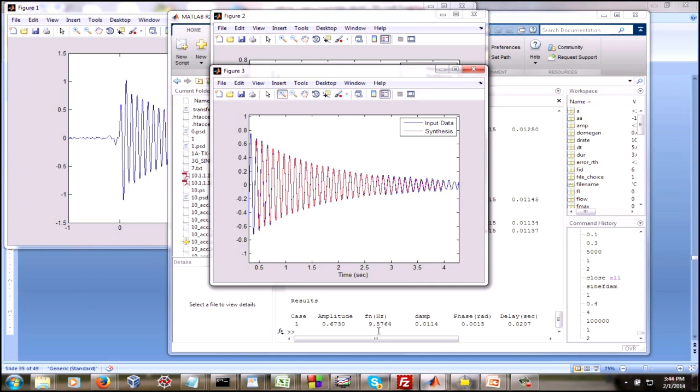And ideally, that's all they would do, is measure the rigid body motion, or you could say the CG motion. But in reality, those same sensors can potentially pick up the vibration as well. And we do not want a situation where the software, the guidance and control software, is mistaking structural vibration for rigid body motion. Otherwise, instability could develop.